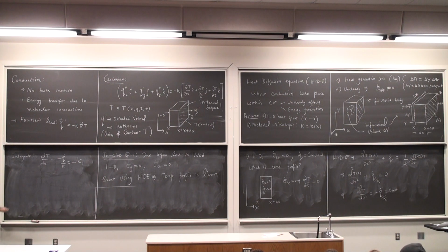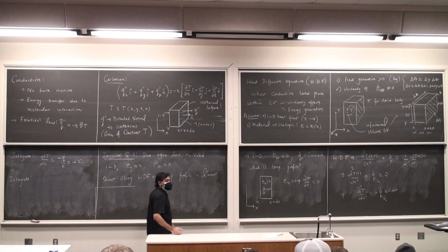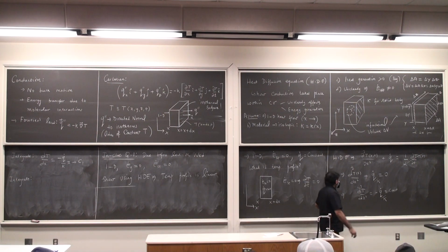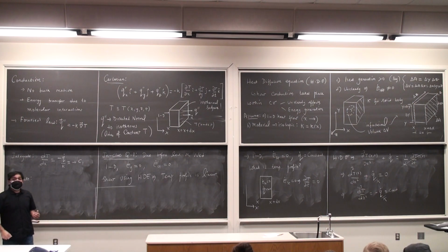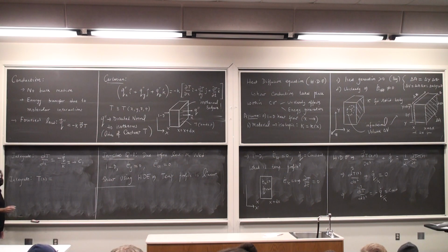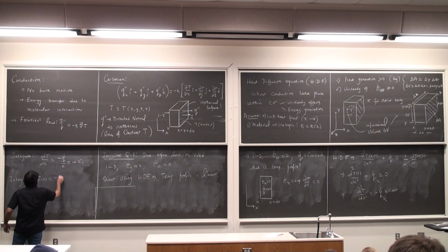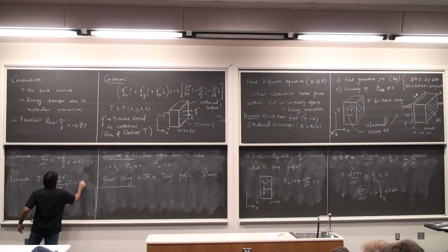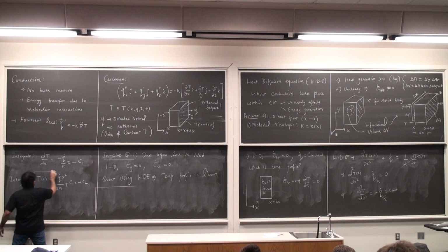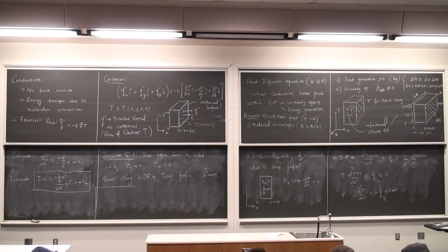Integrate it one more time. I'm assuming you've come across differential equations of that following sort. Just integrate it twice. It's just a function of one spatial variable. Be careful if there are functions of x on the other side, which we will deal with in the next lecture. So this is now T at x, or T of x. T as a function of x is obviously a quadratic. So this is for steady, constant heat generation.